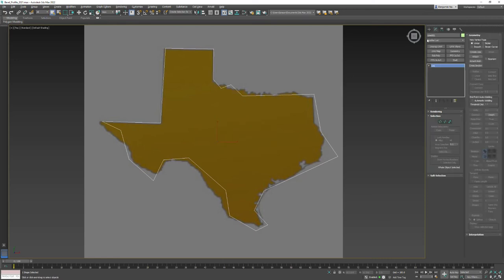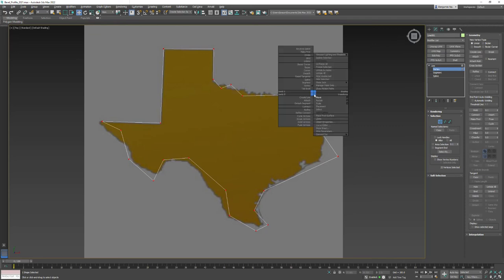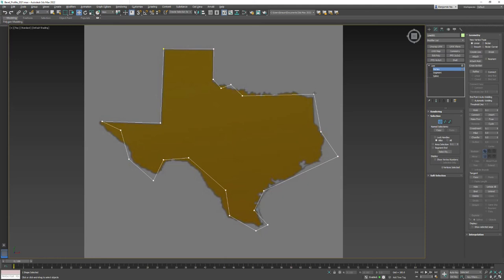We're going to go over to Modify now, because once you have the raw material in there, now you can go back in and start refining it, like I've said in the basic geometry tutorials. I'm going to click on the little arrow. I can go into Vertex. Now I can start grabbing my points. Oops, I clicked on Segment. Click on Vertex, right click, go to Move, and now I can move it around. Let's go ahead, let's grab all these points, right, region select them, and then just hover over one of them, right click, and go over here to Tools 1, and go up, and we're going to make sure these are all set to corners.